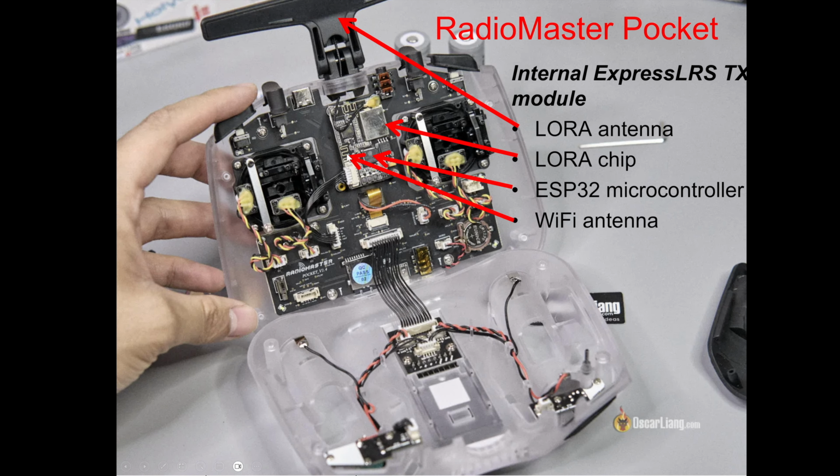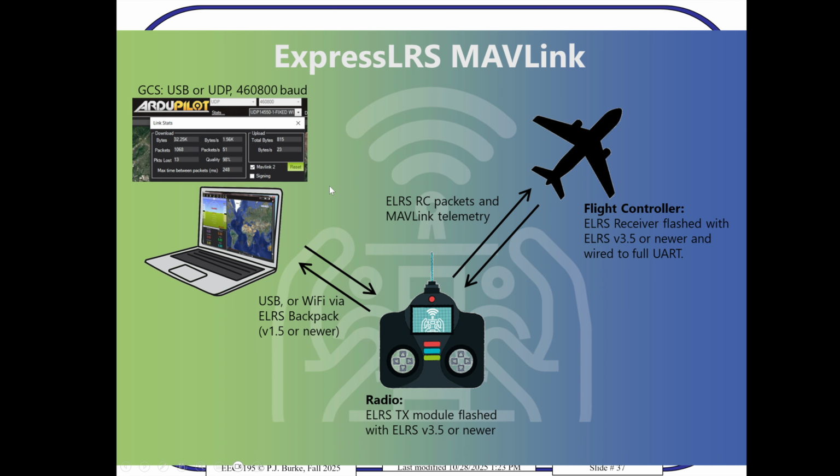And then there's a little Wi-Fi antenna on here. So inside of your transmitter radio is a Wi-Fi radio, which you have not yet used. Now we're going to use it. So you have to flash some firmware to enable that Wi-Fi. And then your radio, if I go back here, your radio will use the internal Wi-Fi as a hotspot. And then you can log into that hotspot just like I did here with Mission Planner. So that's all we're doing. And the rest of it is details.